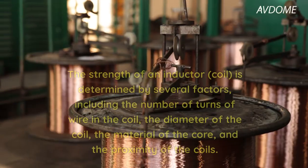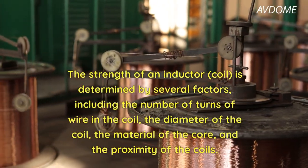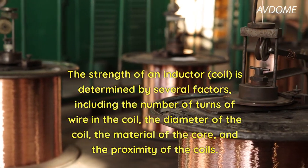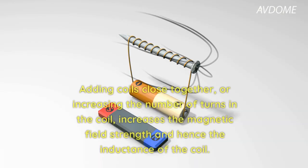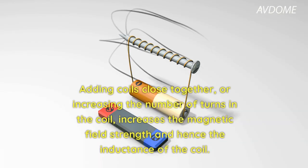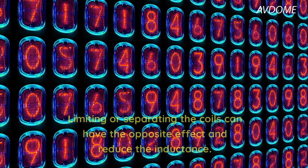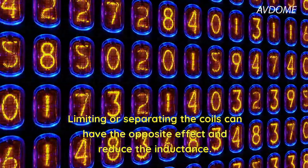It is C. The strength of an inductor coil is determined by several factors, including the number of turns of wire in the coil, the diameter of the coil, the material of the core, and the proximity of the coils. Adding coils close together, or increasing the number of turns in the coil, increases the magnetic field strength and hence the inductance of the coil.